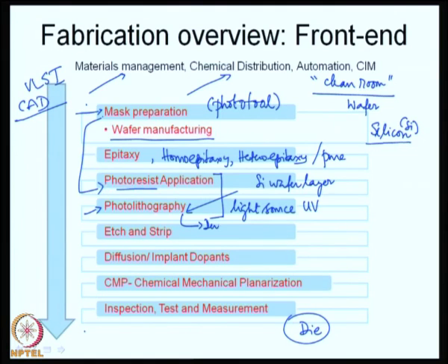Some of the areas are protected by the mask, some of the areas are not protected. Therefore, those areas which are exposed to UV light will get physically changed, and therefore, they are also going to react with certain chemicals during the process of developing. So, the next step, photolithography also includes a step called developing, which will now define the image that you want to generate.